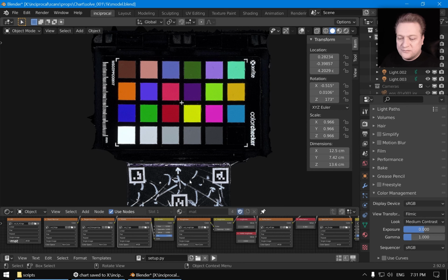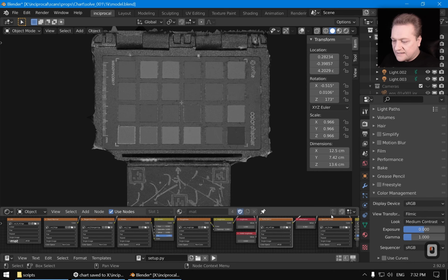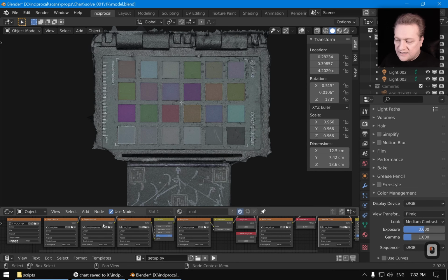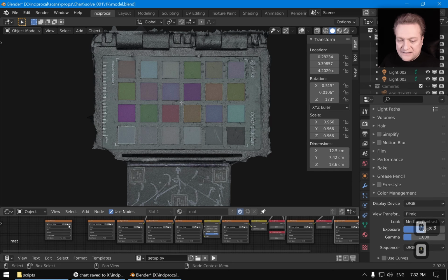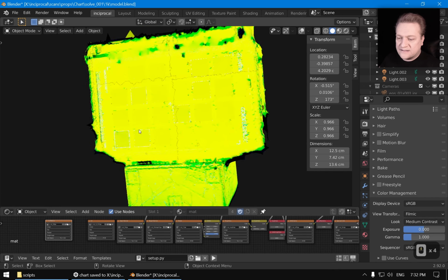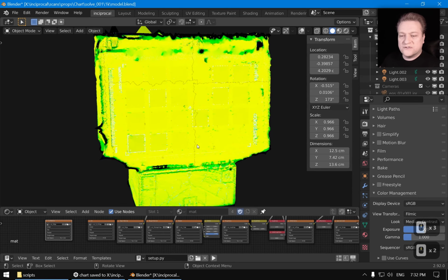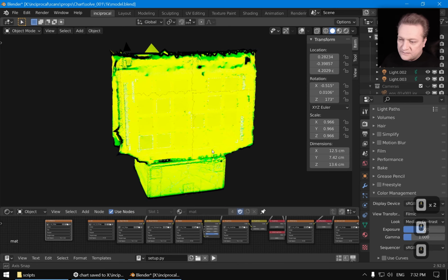Normally that value would be around 50. That's our roughness, that looks pretty consistent, reflectance, and that's our color. And if we zoom out a bit, this is going to be our confidence map, and here we could estimate and see where the problems are and what's reliable and what's not reliable.